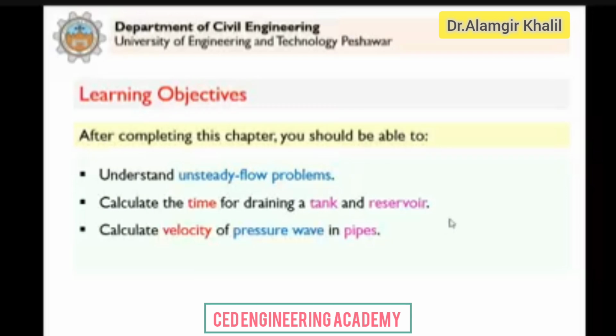Similarly, to calculate the velocity of pressure waves in pipes. This is a very interesting and important topic that we are going to study. When water or any liquid is flowing in pipes and the liquid is suddenly brought to rest, for example when we close the valves, we are destroying the momentum of the water because we suddenly bring it to rest.